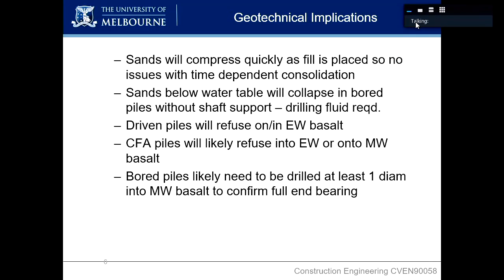So let's hone in on the piles and the geotechnical implications. A few things, high level, more of interest than actual calculation-wise, but there's no time-dependent consolidation required for the project, so that's definitely beyond scope for your specifying. We've got sand near the surface. We know from our first few weeks with Nick Morgan and a few other lecturers talking about boring piles in sand can be tricky because the sand just keeps falling in the hole. So there's ways and means. Drilling fluid is one of those means.